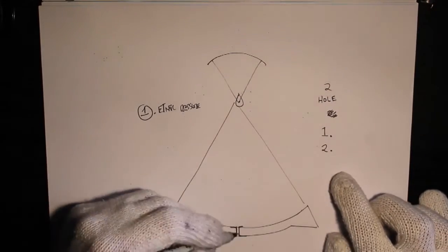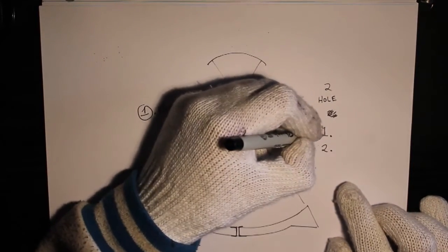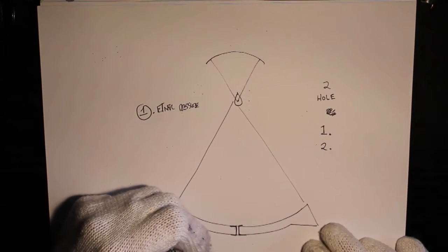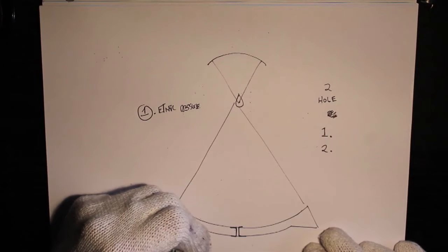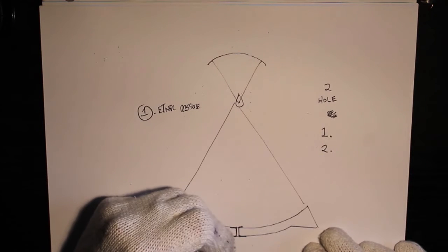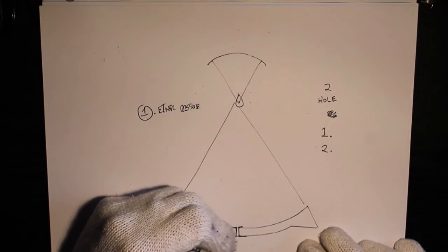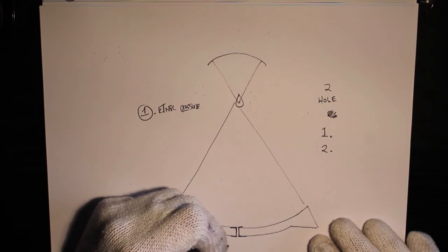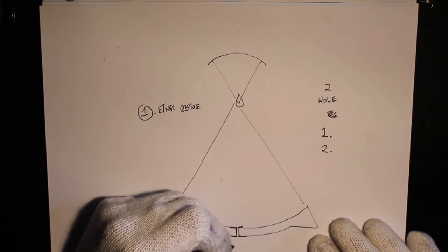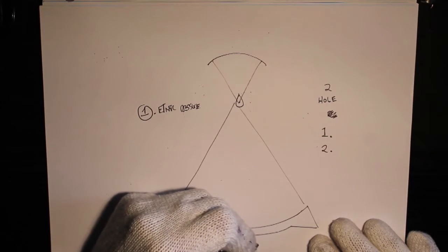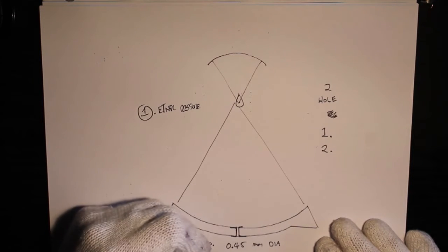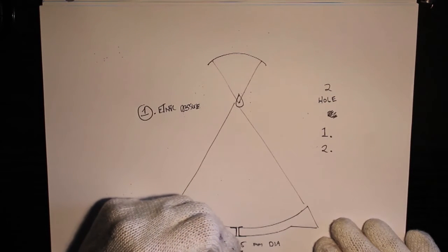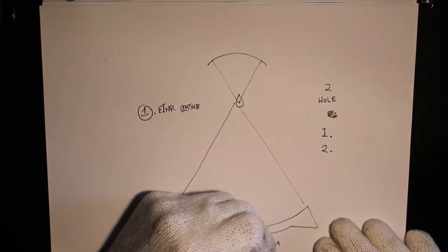The second reason is to do with the tuning, but first of all, the hole's primary function. It's only a little hole. For the base that I have, which is 330 millimeters in diameter, the hole range is about 0.45 millimeters in diameter to 0.85 millimeters in diameter, because it must fulfill two requirements, so you must accommodate both.